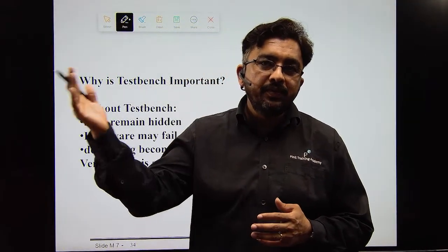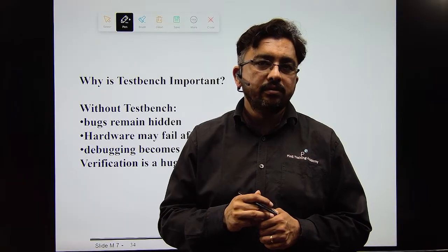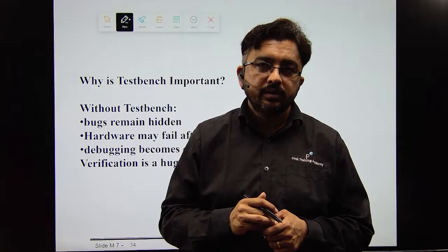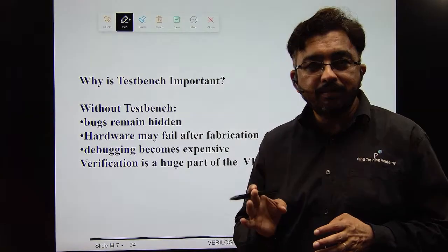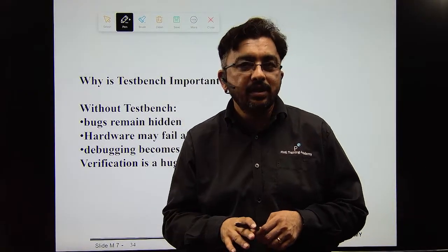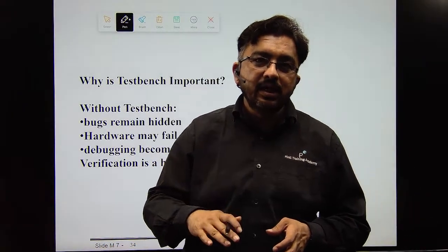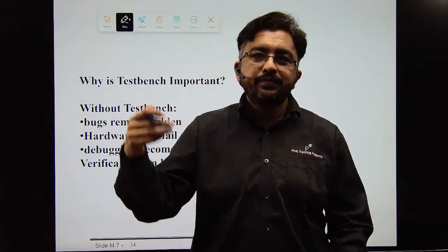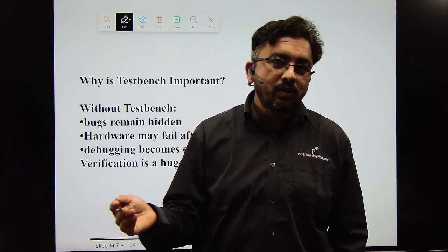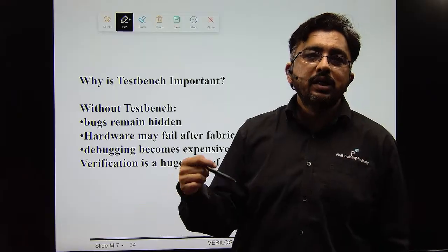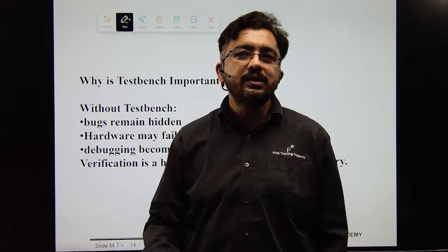Your design may fail after production, and then it will be a huge loss. That is one simple aspect. I'm not saying it failed only because of the test bench, but for many reasons. Maybe the designers have cleared all the aspects, but it fails in the STA stage, the synthesis stage, the PNR stage, the layout stage, or the circuit stage. At any stage it can fail.